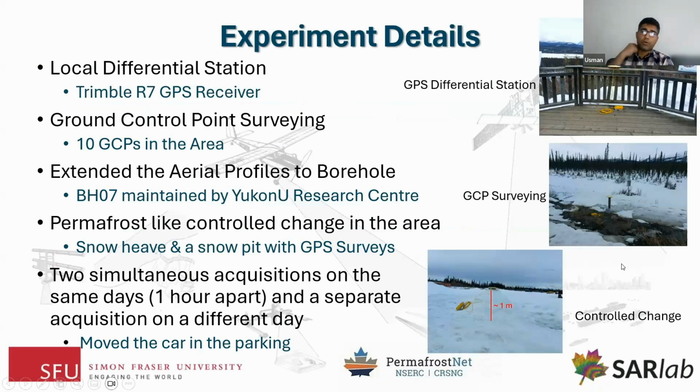There was a borehole in the area, which was being maintained by Yukon University's research center, as well as a weather station which had clear markers which I could use for ground control points. So I surveyed those points. There were a total of 10 ground control points that I surveyed.